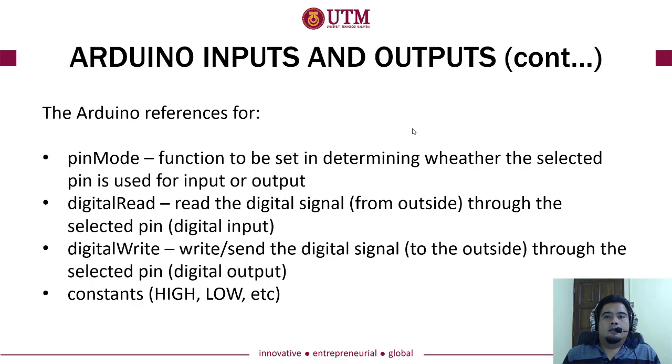So again, that's why I said most of the Arduino ports can be assigned at one time either as input or as output. In order to select this option, you need to run this function, because it will set the port for you, whether you want that port to become input or output.